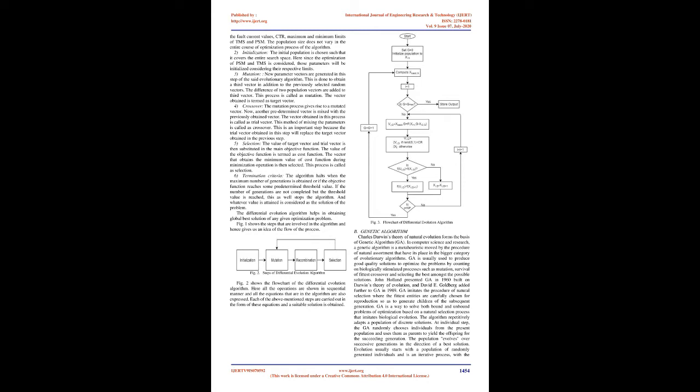The backup protection must pause for the primary protection to function, prior to issuing a trip command to its connected circuit breaker. There will be an intentional delay period between the operation of both relays. The relay close to the fault will experience maximum fault current and hence will trip faster. The delay between the operation of both relays is called the coordination time interval, which comprises the overshoot time and the time of operation of the circuit breaker of the primary relay.